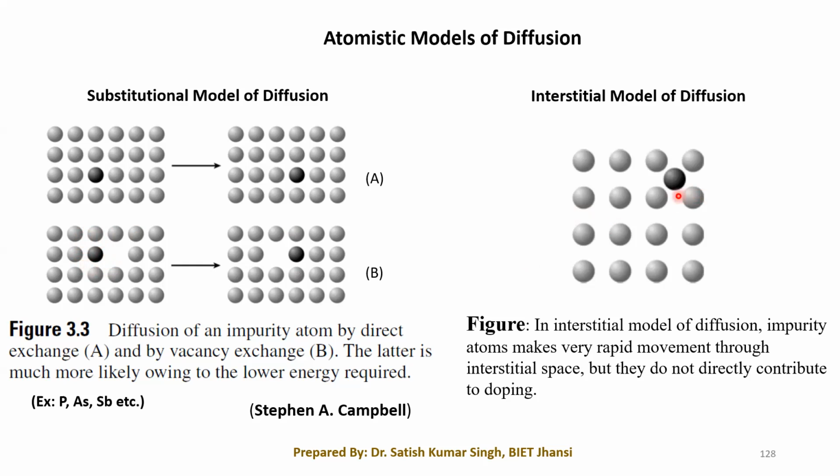But here you can see that the impurity atoms at the interstitial sites are not forming any bonds, nor breaking any bonds whenever they move through the interstitial spaces. Nothing like that happens, as it did in the case of the substitutional model.